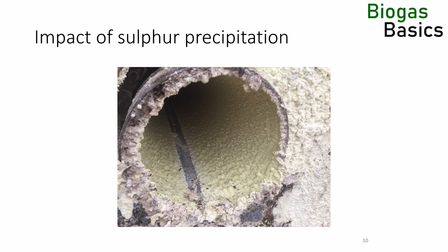The reduction of diameter, the uneven surface, and the moving water surfaces will all add to the friction factor of the biogas flow, increasing its pressure drop in the pipe. Oxygen is often added for desulfurization, but even if it is not added deliberately, it can diffuse over the gas holder membranes or can be introduced by the feedstock. So, the gas lines will experience fouling over time. Make them big enough.